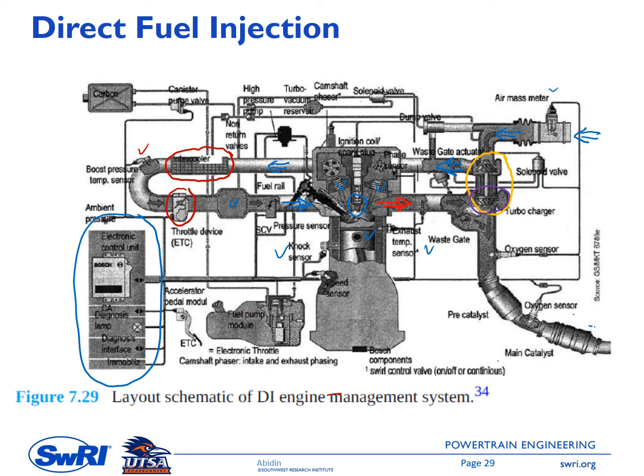You see here, this is a bypass path, okay, and then it will flow to the aftertreatment system. So we have an oxygen sensor. We will see this oxygen sensor in the next slide. And then we have a pre-catalyst, and then another oxygen sensor, and this one is the main catalyst. It very probably is a three-way catalyst.